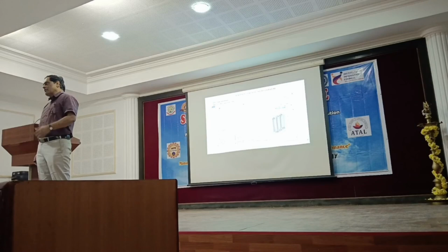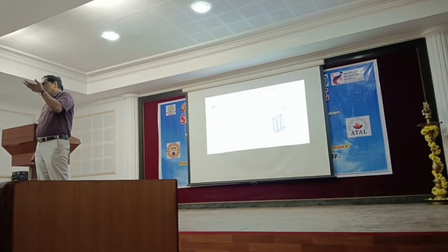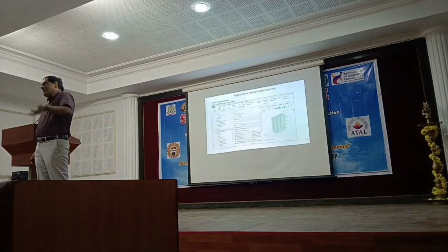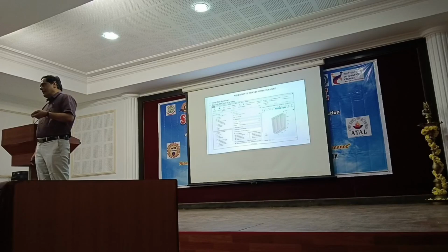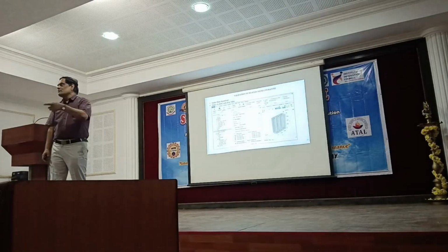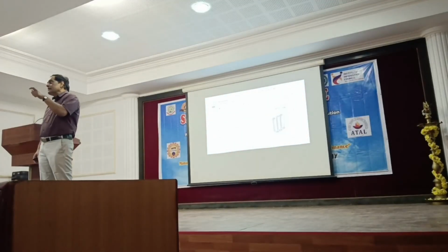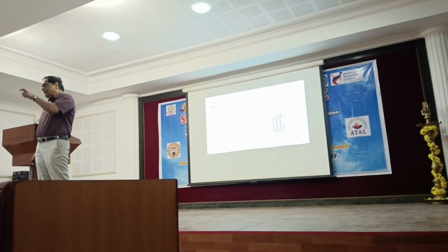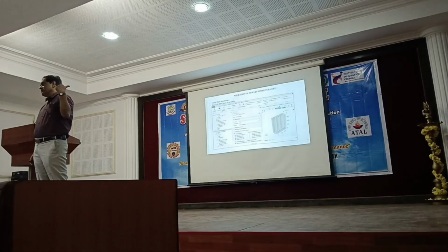You can create the geometry of the particular battery pack. You know what inputs are required. I already highlighted all of it: the cathode properties, anode properties, the dimensions. Everything is available in the input database. Choose the model, choose the particular geometry of the battery pack. COMSOL is basically multiphysics software wherein we have an exclusive module for battery pack simulations.